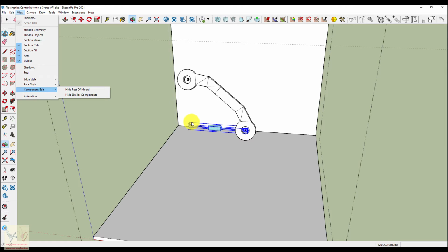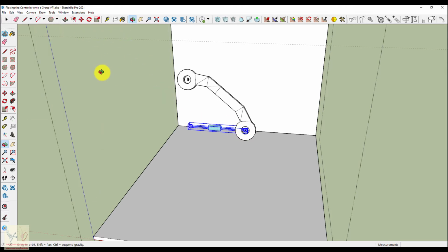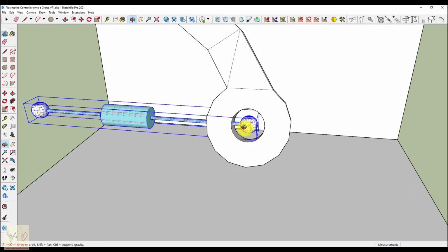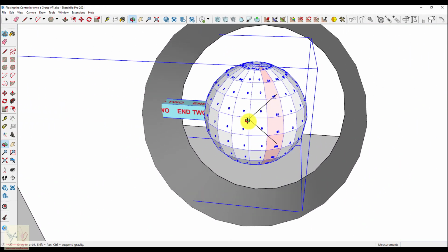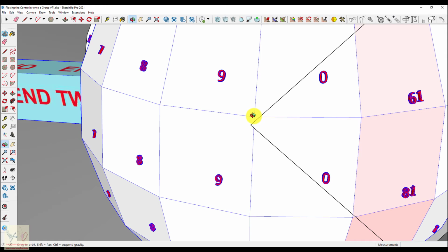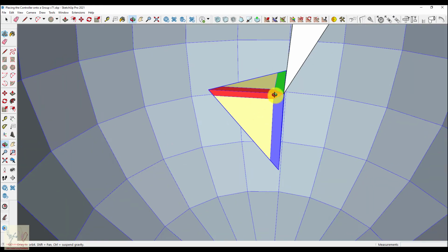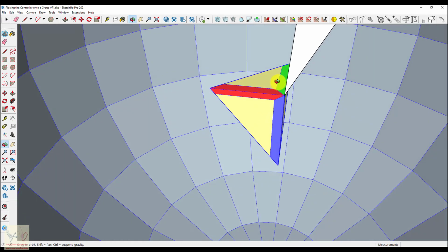And what you have to do is go in here to your rotation capabilities. So we're going to let the red axis be the long axis of this device. So the only other rotation options we have is rotating on the green axis or the blue axis. So we'll take the blue.